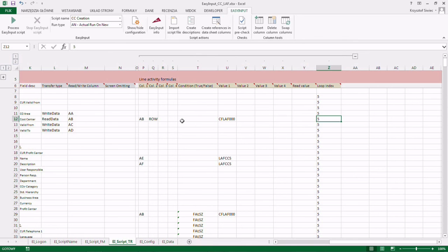And also, if the script is an extended script, then the value read will be put here so that it could be used in the formulas below in the next lines. And you can also read the processed row number, not only the value of the cell. So sometimes if 4 parameters are not enough, you can read just row numbers and in the formula access the parameters in that row, as many as you would like to.